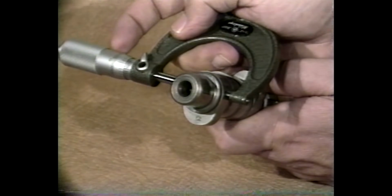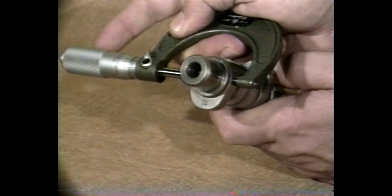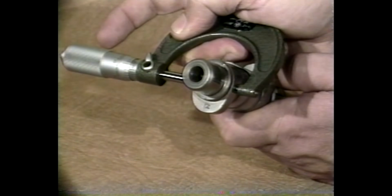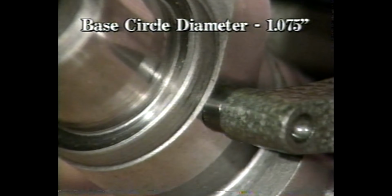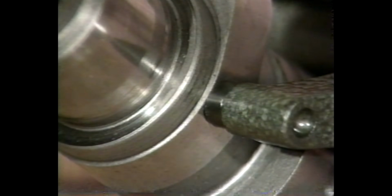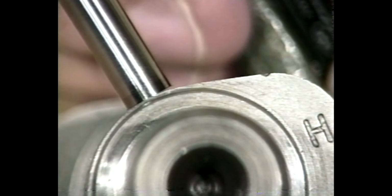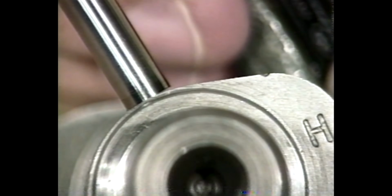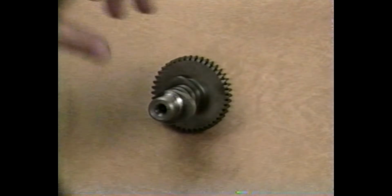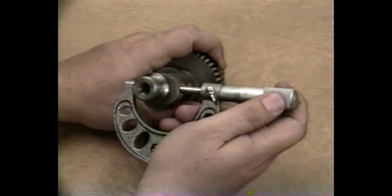For this type of cam, we can use a 1 to 2 inch outside micrometer to accurately measure the base circle diameter, which is 1.075 inches. We must ensure that the anvils of our mic are not on either of the cam lobe ramps, so that our measurement is accurate.